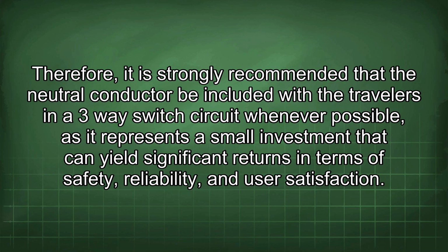Therefore, it is strongly recommended that the neutral conductor be included with the travelers in a three-way switch circuit whenever possible, as it represents a small investment that can yield significant returns in terms of safety, reliability, and user satisfaction.